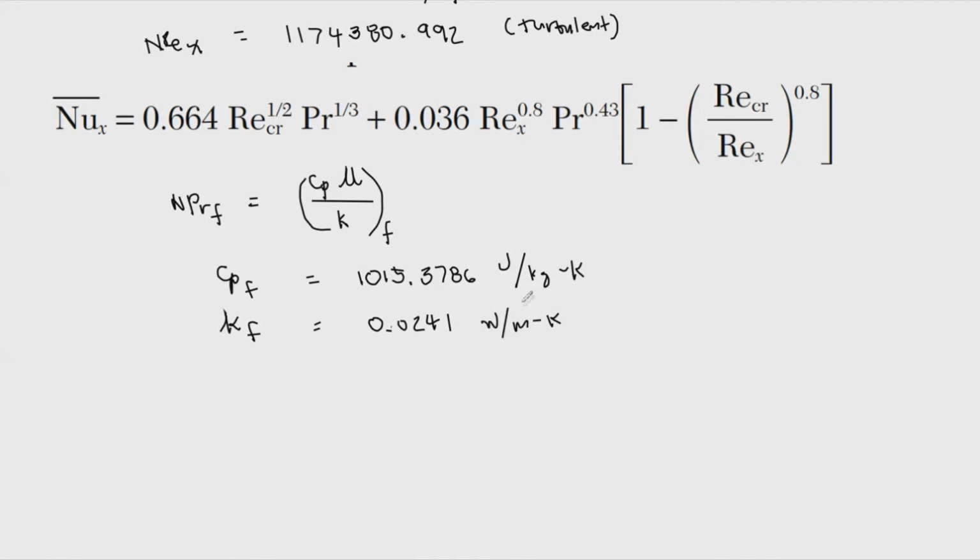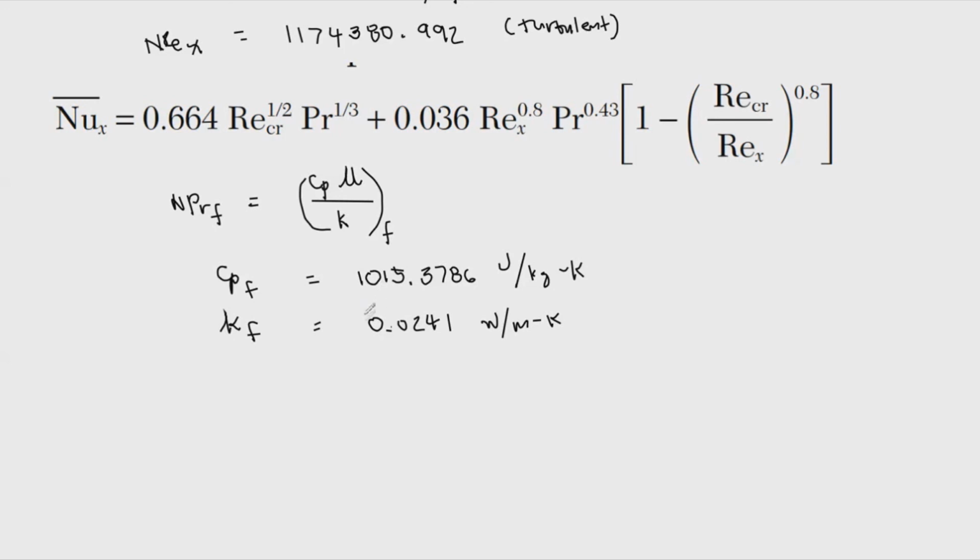And as you can notice, the thermal conductivity of our gases are almost the same, around 0.02 to 0.04. So the values of our thermal conductivity should lie along those values. And if you've gotten something like 100 for thermal conductivity, then you might need to review your answer since we're considering gases there.